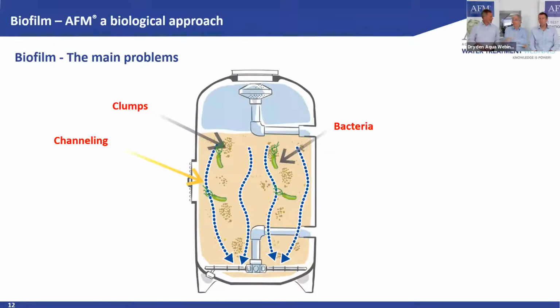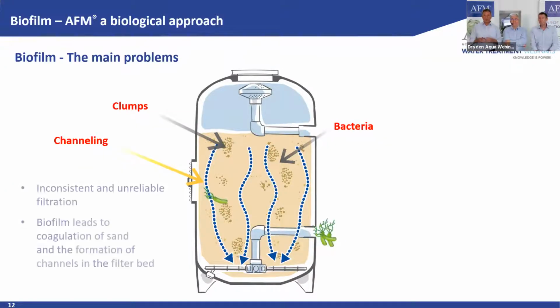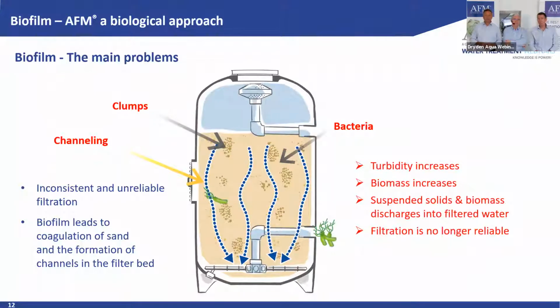Especially in wastewater treatment, as we talked about today, this is very important to understand. From time to time when these channels open, you have a breakthrough of biofilm formation. This is also when you have a high increase in turbidity, biomass and suspended solids. Your filtration is no longer reliable.